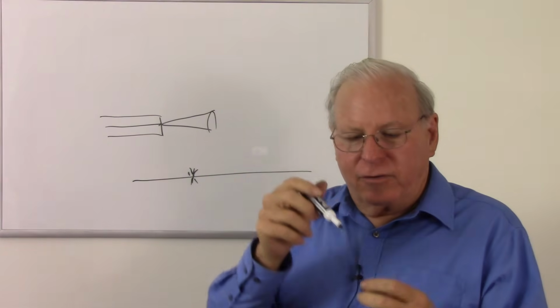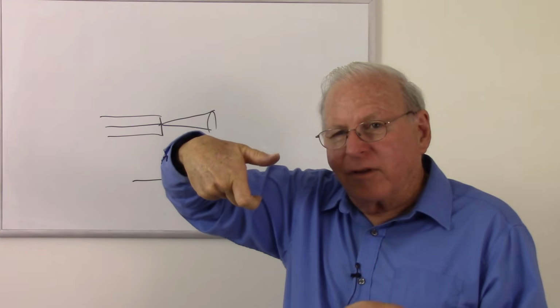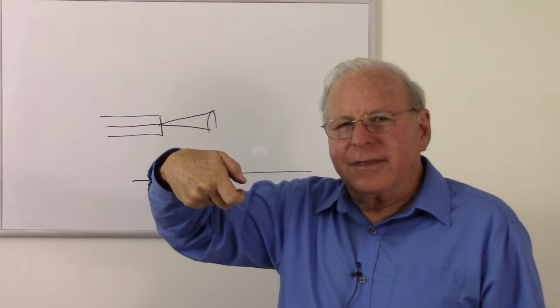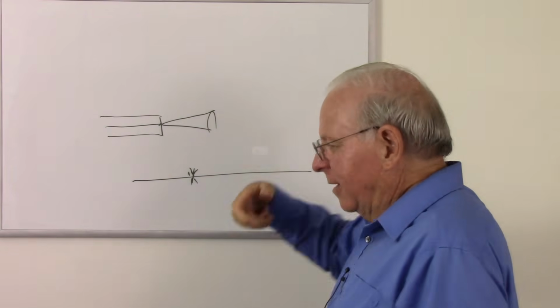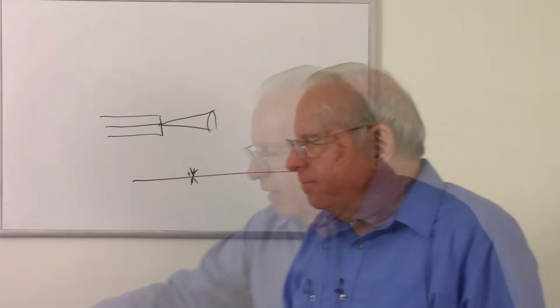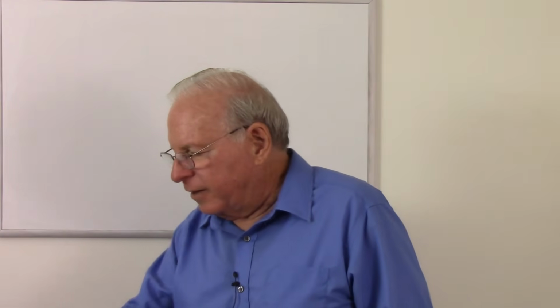In fact, there are ways to get information out of a fiber with a device that hooks onto it and bends it so that the light comes out to a little photodiode that can read the light in the fiber without being at either end or without breaking it. So that's a visual fault locator, just basically a little laser. As an electronics technician, you're probably not going to be testing fibers, but you might.